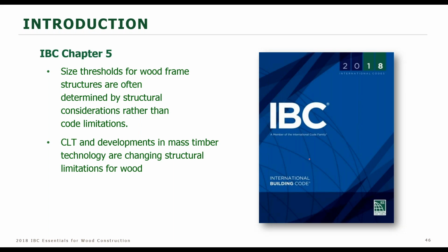What's it based on? Let's go through some basics of height and area in the IBC. It's all in chapter 5, which has gone through some new development in the last few years with new tables and so forth. However, the parameters there have not changed very much at all. They will in the 2021 for the new type 4 construction types, but they have not changed much over the years up through the 2018.